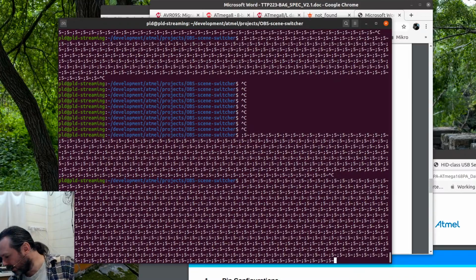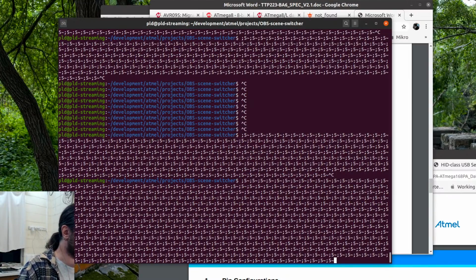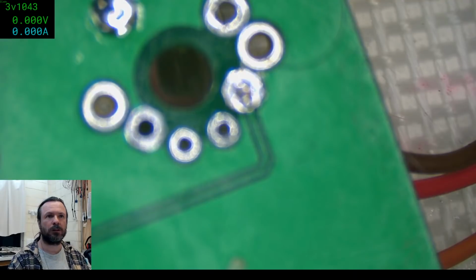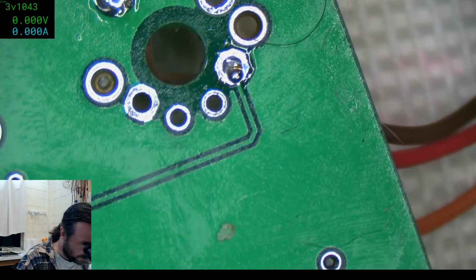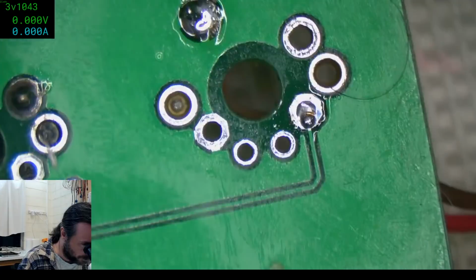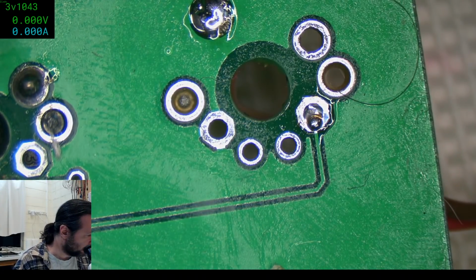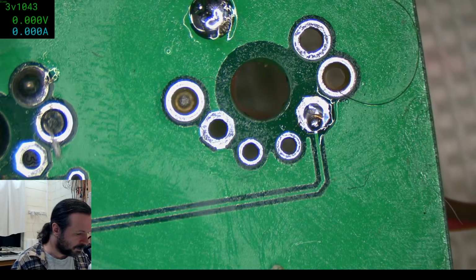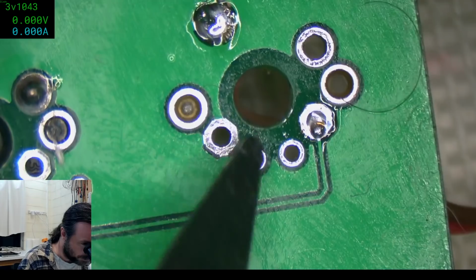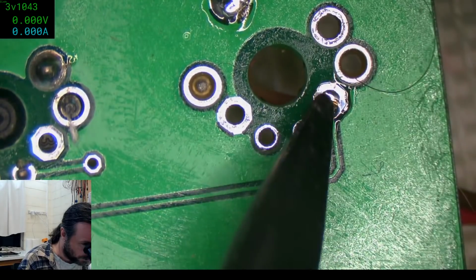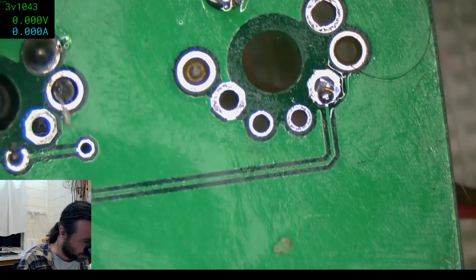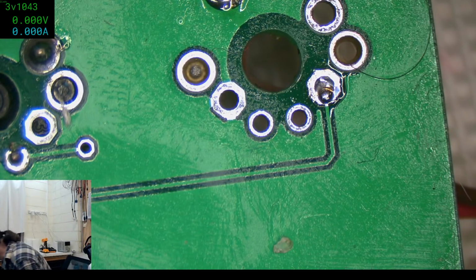Okay. We're going to put a 10k resistor on the switch input to ground. It's not sticky, it's more just it rapidly floats back up and goes out of control. While it's in the presence of the finger, it moderately behaves and then it goes out of control. So yeah, we'll just stick about a 10k between there and there. It may stop it from misbehaving so much.